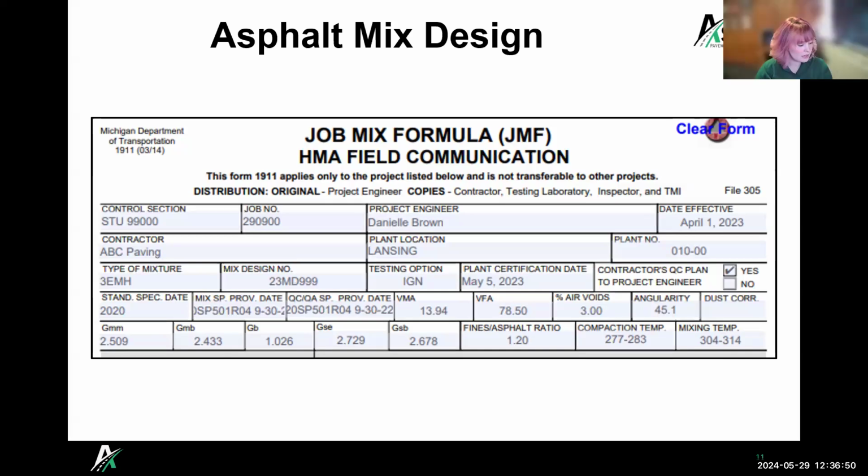Okay. And in terms of your aggregate testing too, are there additional tests besides your LA abrasion, your AWI, your standard sieve, those kinds of things? Are there things beyond that that people might need for a specific project?